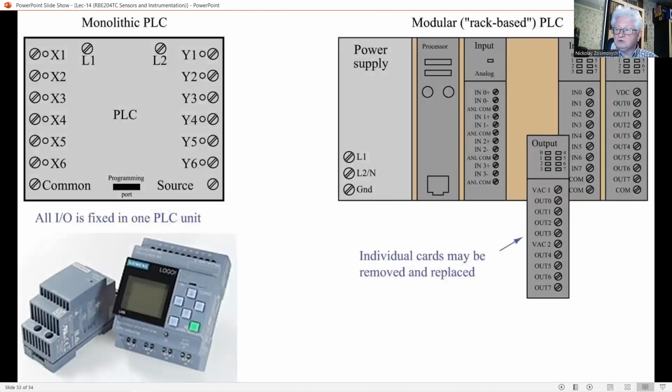In addition to turning on and off the discrete output components in a correct sequence at proper times, a PLC can perform other useful operations. In particular, it can perform simple arithmetic operations such as addition, subtraction, multiplication, and division on input data. It is also capable of performing counting and timing operations, usually as part of its normal functional requirements.